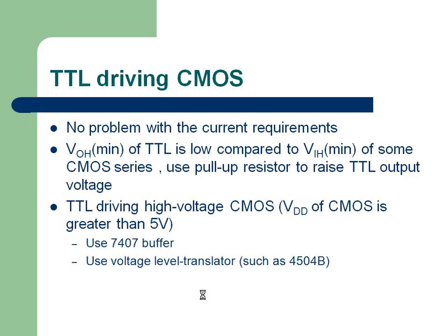So that is TTL driving high voltage CMOS. There are other variants of high voltage CMOS where the voltage levels are very high. Then you need some buffer and so on. It's practical stuff which is not required. In principle, the idea is that your VOH minimum is not suitable, you want to lift it, then add a pull-up. In the same way, if your VOL maximum is not good, it is going very close to VIL, so the noise margin for 0 is compromised. What you have to do? You have to add a pull-down resistor to ground. Very simple.